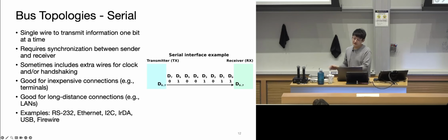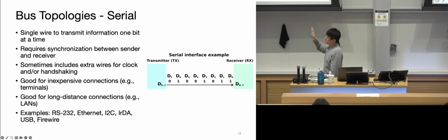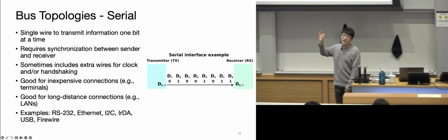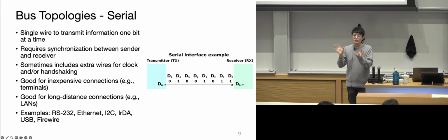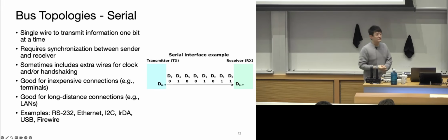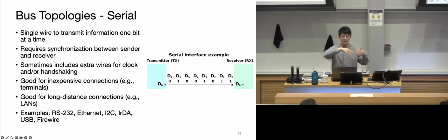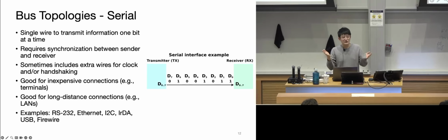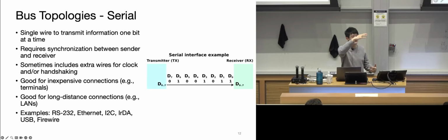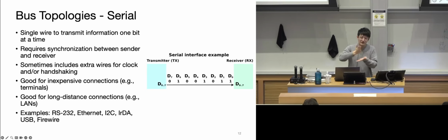Apart from that, we also have I2C or Ethernet with various different protocols. They are all under serial communication, which is also going to be the main communication protocols we talk about in our class for chip-to-chip communication. The reason for that is that for parallel there's not too much to talk about. They use a lot of wires, so the implementation is pretty straightforward. They have their shared clock as well. You just clock.